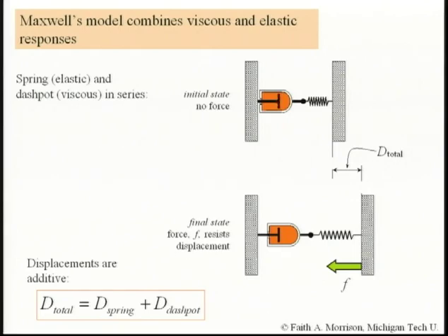So while that's retracting, it's going to be generating a stress also. And that stress is due to a sort of a Newtonian contribution. So if I pull these things apart, it will pull apart, and then the spring will slowly pull them back together, but they won't come all the way back together because there will be some displacement of the paddle inside the shock absorber.